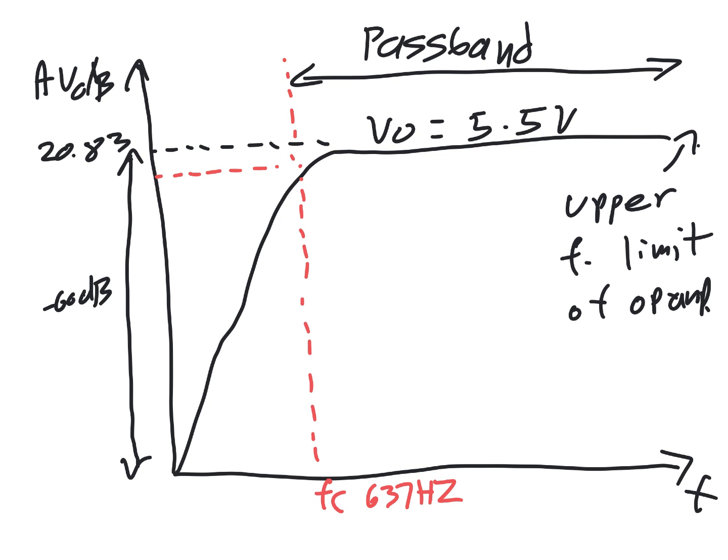So this is at minus 39.17 dB, and this is at 1/1000th of FC. The gain is now minus 39.17 dB, so it's attenuated. But it's 60 dB down from the passband gain of 20.83. This point right here.